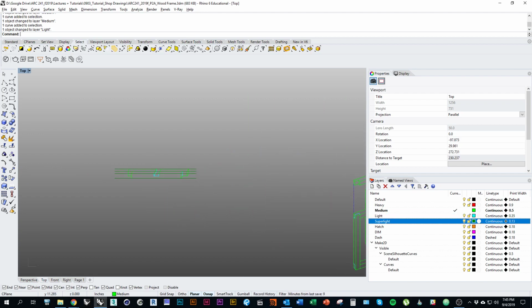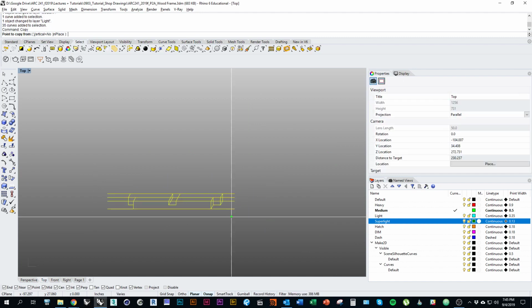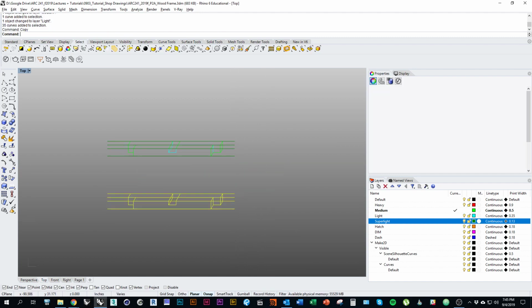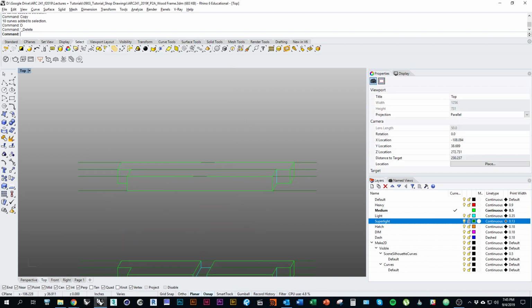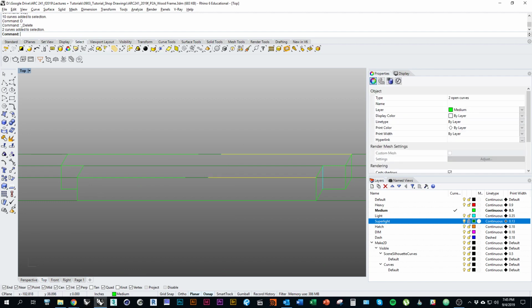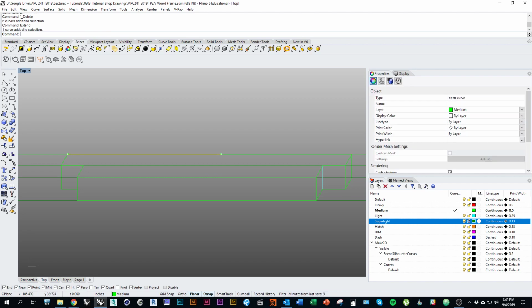And in this case, I'll actually just make it easy and copy the whole thing. So obviously we don't have the joint in the middle on the ends, or I'm sorry, on the uprights. Now to close that gap, I could draw a new line. I can also select these 2 lines and type in extend. Click on the opposite line, and it should just extend right to where they meet. So now those 2 lines meet.